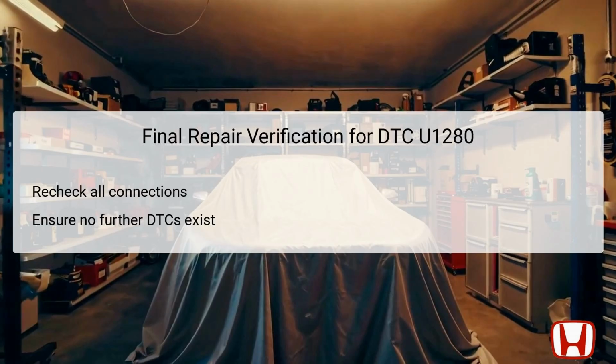Once repairs are completed, it is vital to perform a final verification. Start by thoroughly rechecking all connections, ensuring that every component is securely connected and free of corrosion or damage that could impact performance. It is also important to use the HDS to check for any remaining DTCs to confirm that the system is indeed functioning correctly after repairs.